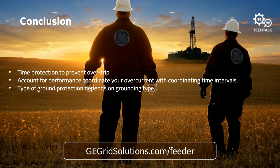You take the relay out of the 750, after you've de-energized and followed your company's policies. You take the case out, put the 8 series case in, plug the terminal blocks back into it, put the 8 series into the case, and re-energize the relay.